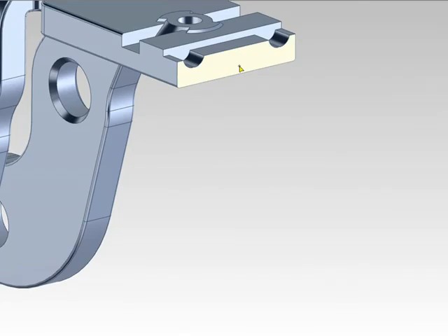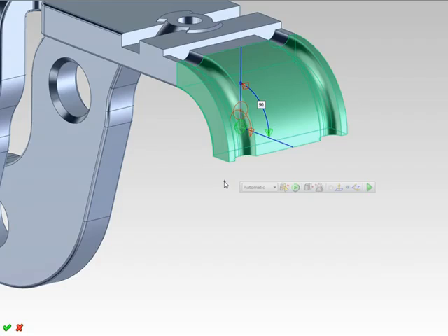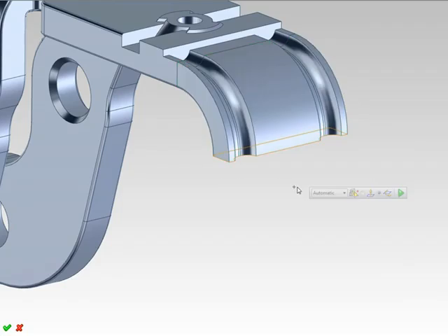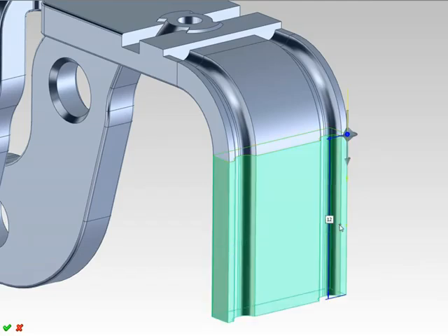Angular pull combines the turn and bore. I can select a face or a profile, define the direction of the pull, and dynamically define the angle or give it a precise value for the angular pull. I can easily switch between angular and linear pull. The command is in the option menu, which you can access by pressing the spacebar.